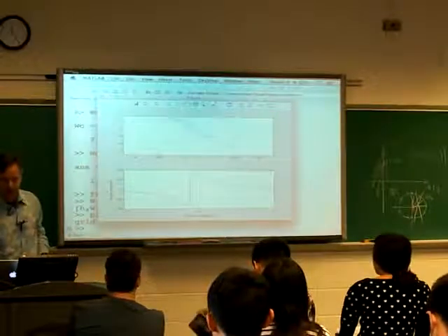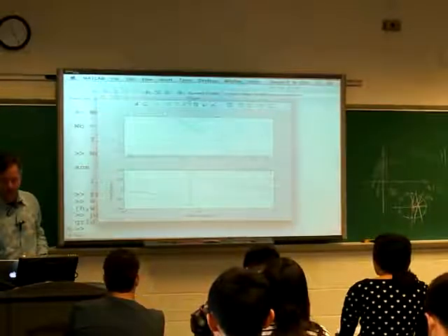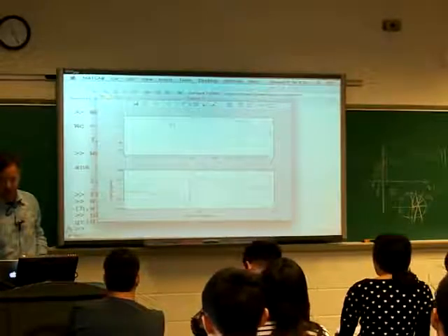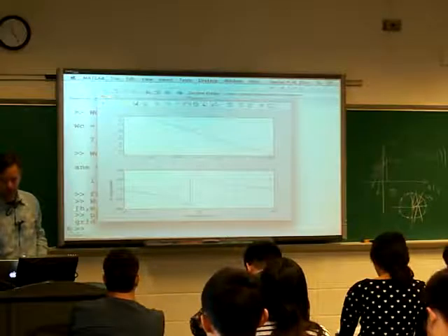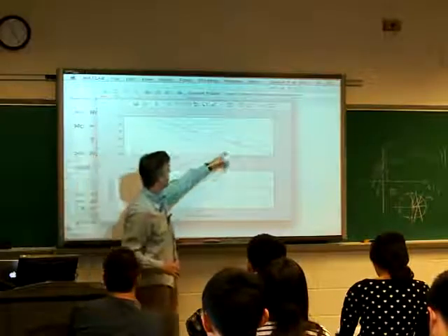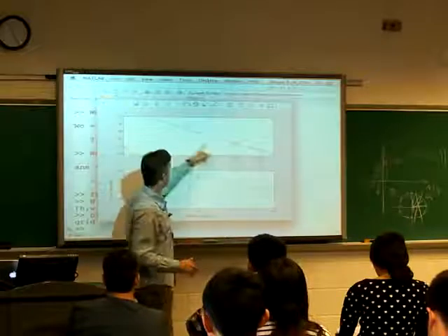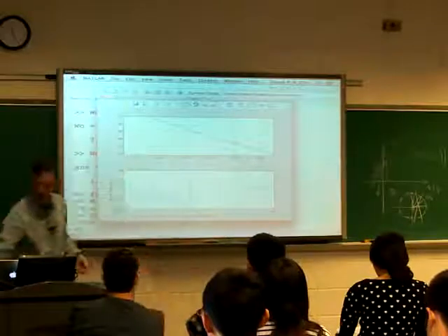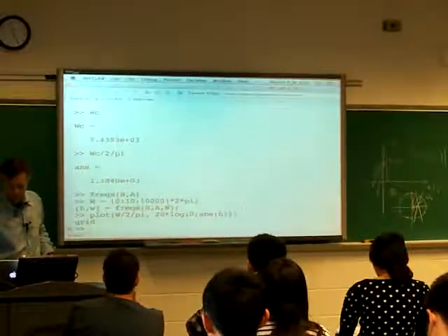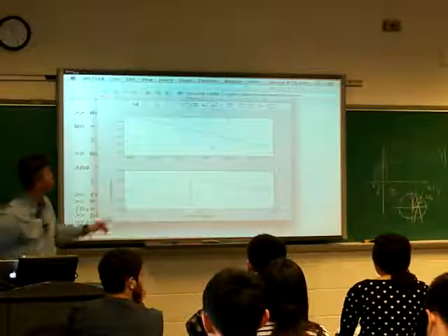And then if we keep following this down, the other constraint was to try and get to minus 40 dB at 5 kilohertz. Turns out we're already at minus 40 dB by 3.8 kilohertz here, right? And then at 5 kilohertz, we're even further down, at minus 50 dB, in fact.